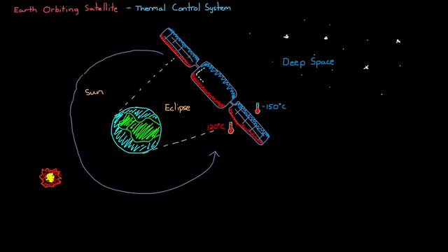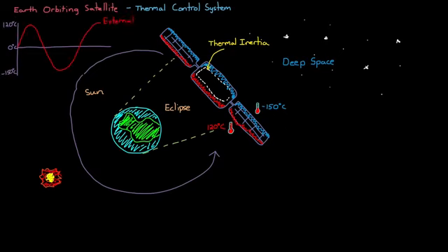The interior of the spacecraft is protected from these extreme temperature swings a bit because they sit within a mass that has some thermal inertia. If you look at a typical temperature plot over time, the external temperatures tend to swing wildly since they're not protected, while the internal temperatures have that low-pass filter of thermal inertia smoothing out the swings and creating a less dynamic environment. Even still, some internal components can see temperatures that are outside of their desired operating ranges, and we need to figure out a way to maintain their proper temperature.